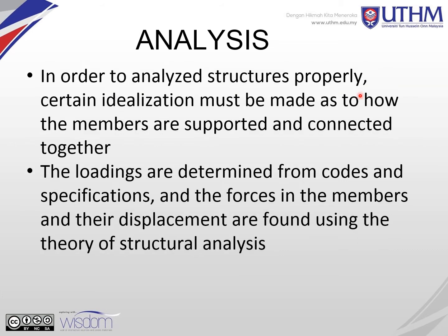Once the preliminary design of a structure is proposed, the structure must be analyzed to ensure that it has its required strength and rigidity. So structural analysis is very important. In order to analyze a structure properly, certain idealizations must be made as to how the members are supported and connected together. So there are assumptions that need to be made. The loadings are determined from codes and specifications, and the forces in the members and their displacements are found using the theory of structural analysis.